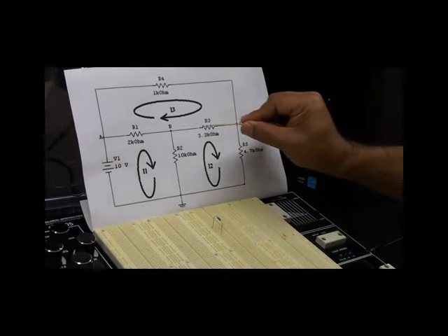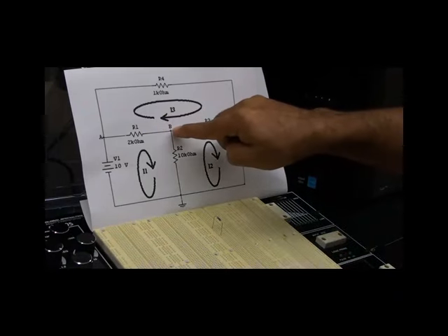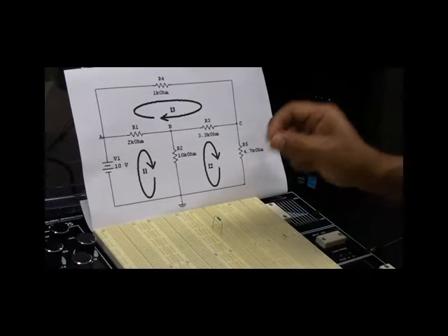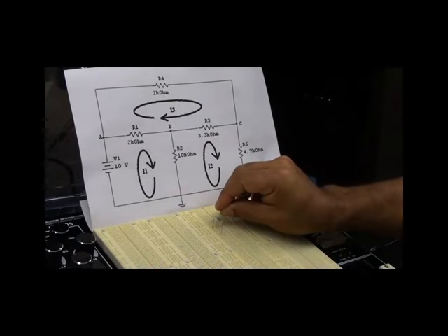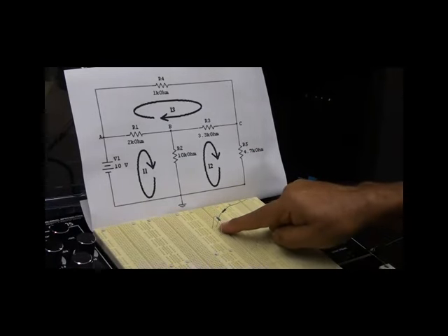Then R3 is another resistor connected to R1, and they are sharing one connection. R3 is after R1, so let's first share the connection. I have to insert one pin exactly in the same column where the holes are connected.